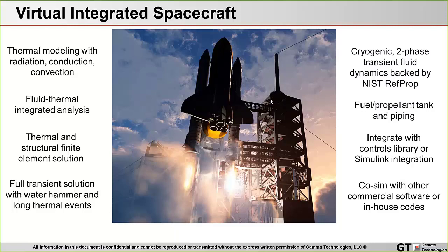That can be integrated with a thermal structure and solving all three modes of heat transfer, whether it be radiation or convection or conduction. And this analysis can be fully transient to investigate either steady state or actual transient long time scale events or short time scale events to study things like water hammer.